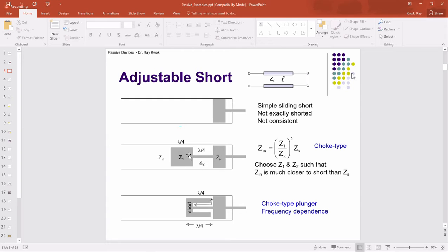So, and if you want to make this, well, this is a very long length, quarter wave, can I make this smaller? Yeah, you can fold this. So you can fold the last block into here. So from here to here is quarter wave, from here to here is roughly quarter wave. So you still have an open to short, short to open kind of transition. Think about this, right? Maybe it doesn't sound like a big deal, but when you try to use this, you will come back to this.